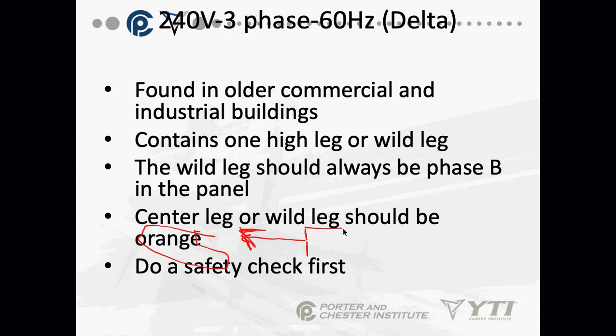Again, do not trust the markings on this. These are old systems. Wires have faded, marking has gone away. Someone asked about the yellow earlier. Orange could look yellow, and will eventually look white. Don't trust these wire colors on this.